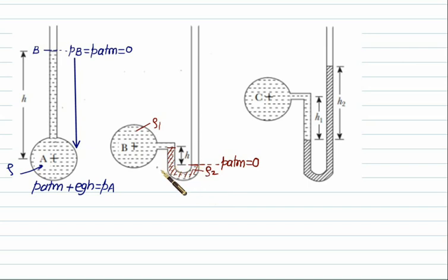So this one is our x-axis. So the pressure here and the pressure at this point remain the same. So it will be the same as P atmospheric. From this point, that is from point A, we want to move to B. Since from A we want to move towards B, we are moving in an upward direction. So we have P atmospheric, that is the pressure at A. Since we are moving upward, we use a negative sign, and the column change is rho multiplied by g multiplied by h. This time the column is of density equal to rho 2, and this level is the same, so the pressure remains the same. Finally we come to point B, so we can comfortably measure the pressure at B.